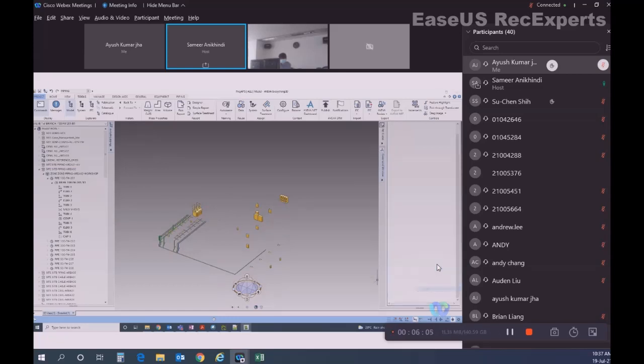Now see, I have changed this model. Whenever I change, the hierarchy becomes a little bold. The owner hierarchy and the element which you have changed, for example when I rename a wall, becomes bold. The bold hierarchy means you have claimed that hierarchy.